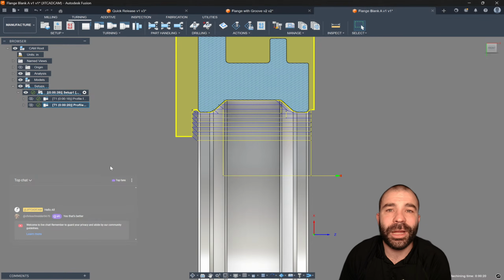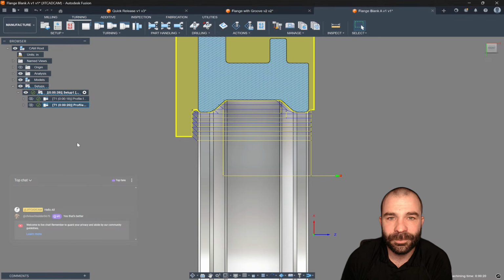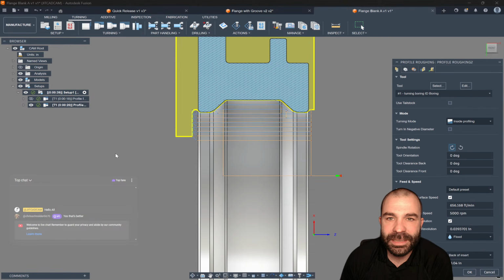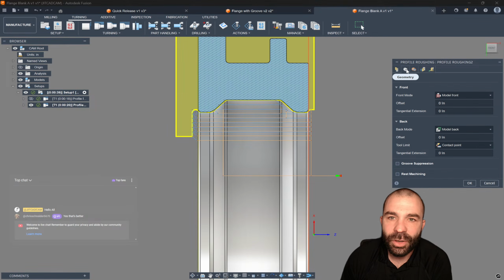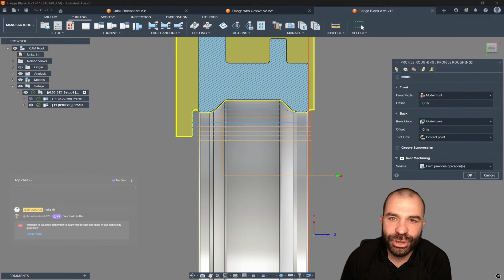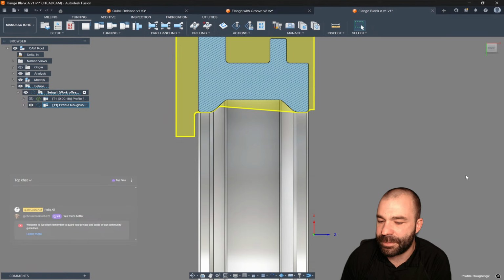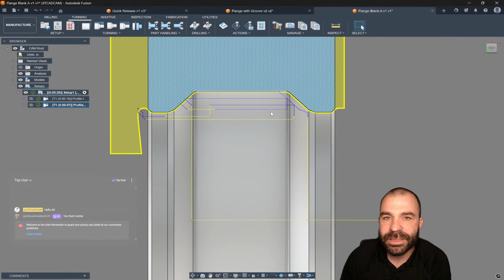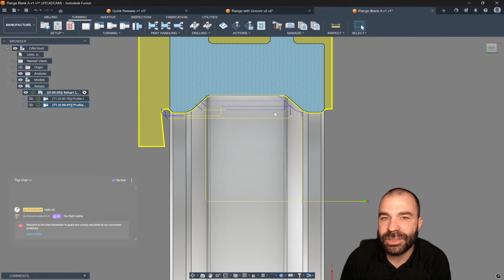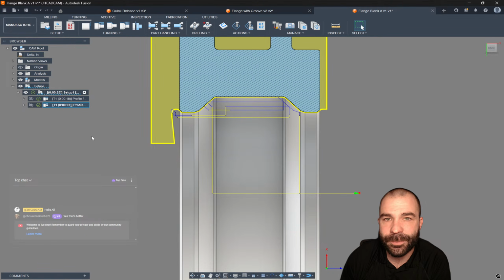It's not really meant for heavy boring stuff like that. So let's now take our two toolpaths and get them merged down and combined so that they work together. As you're going to see, I'm going to go back into that toolpath real fast here. I'm going to turn on rest machining for when we're using that VNMT cutter. And as you can notice now, we have automatically trimmed that down to whatever leftover material is still there. We can use that to clean it up based on what's happening.